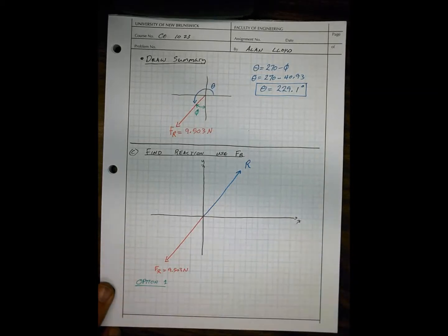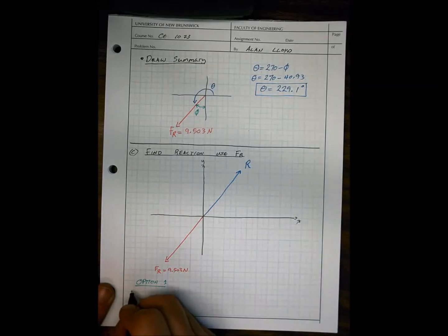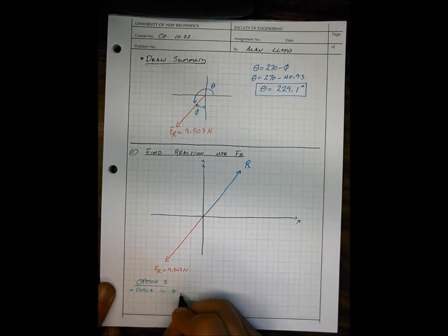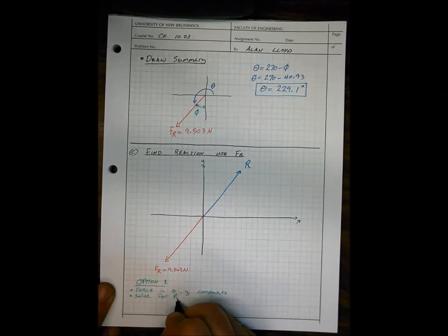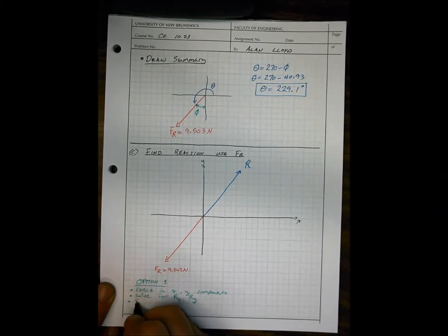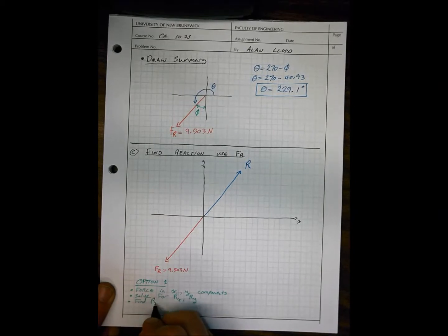In option 1, we'd have force in x and y components, solve for Rx and Ry, then find R and find theta R.